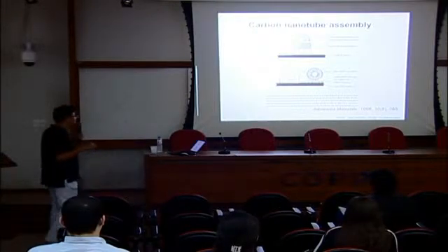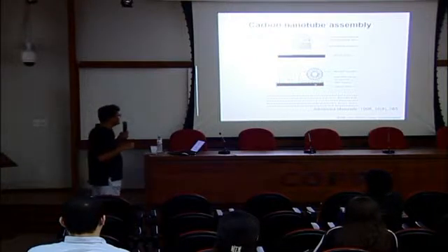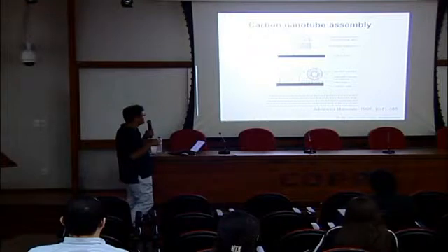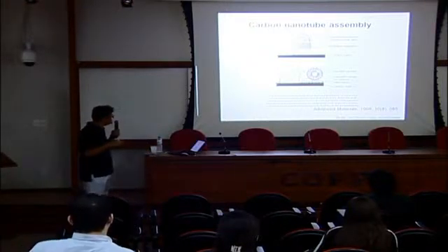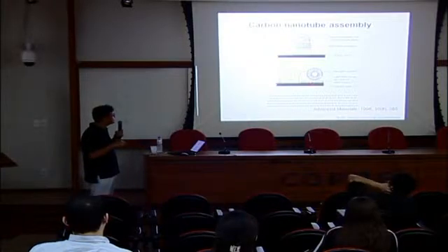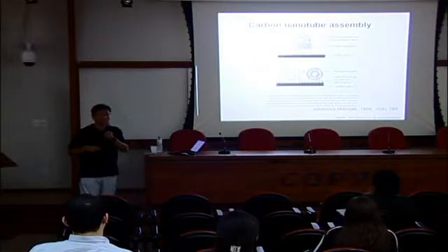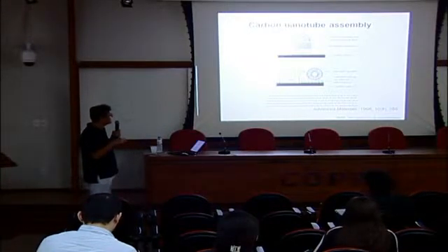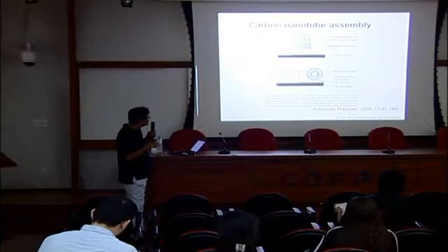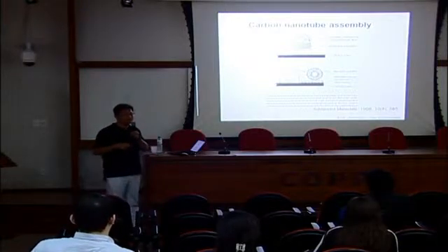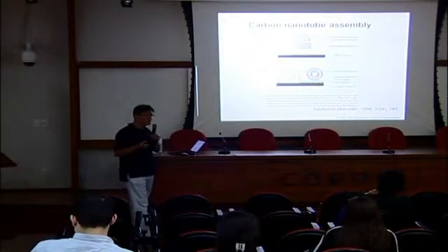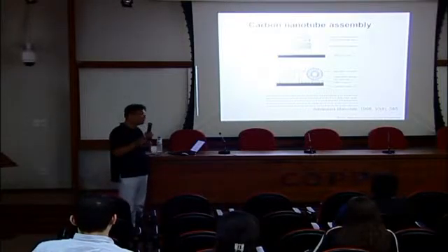For the bottom case, the oxide layer is chemically positively charged, and the gold layer was coated with a carboxylate, which is a negatively charged ion. Then this negatively charged carbon nanotube will prefer the positive side, not the negative side, because the charge interaction is attractive on one and repulsive on the other. The thing is, sometimes, even though a negative charge does not like a negative charge, it can stay on top. That's probability. Conventionally, the success rate of this self-assembly is about 50 to 60%. It's not that low, but it's not that high.